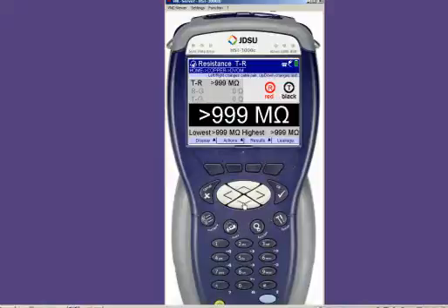Well, how high do you read, Jeff? Well, greater than 999 million ohms, almost a gigaohm. Orders of magnitude higher than what most phone companies use as a pass-fail parameter. Logical question might be, well, why do you measure so high? Well, personally, I think there's a bit of marketing involved. I can remember when test sets read greater than 10 meg, someone moved it up to greater than 100. One of the prominent manufacturers were the first to go to greater than 999.